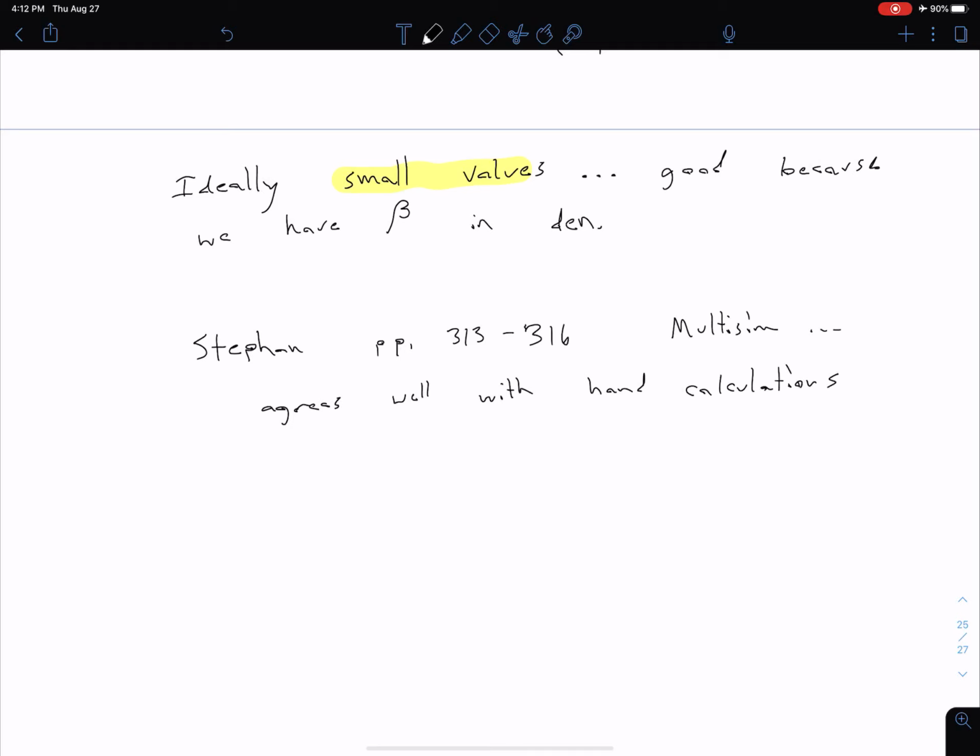The caveat is that this is true while our BJTs are in the forward active mode. As soon as they go into saturation, the agreement isn't so good. But of course, as we set out, we said we're making a lot of assumptions. We don't expect this to be super accurate, but it should give us a pretty good first order understanding of what's going on. And we see that is true.